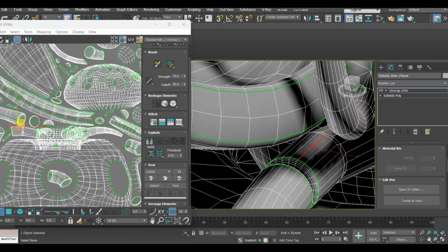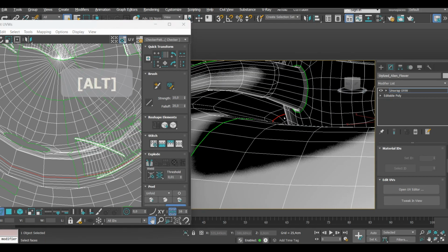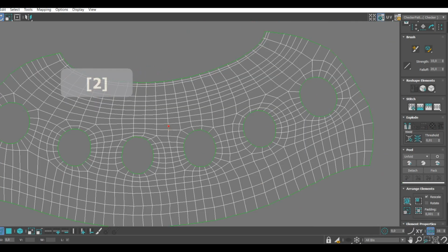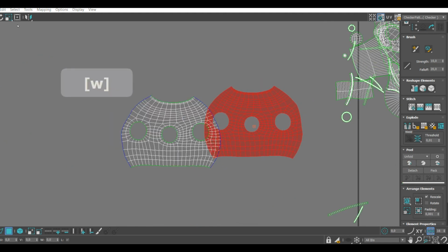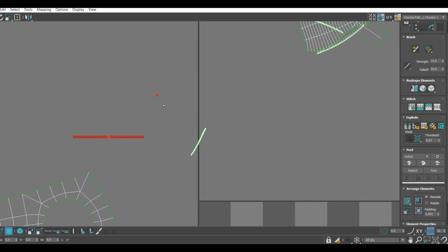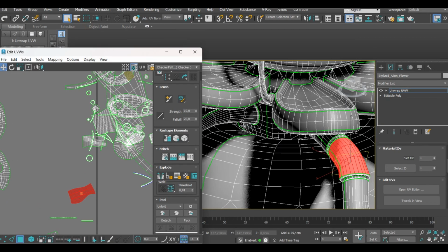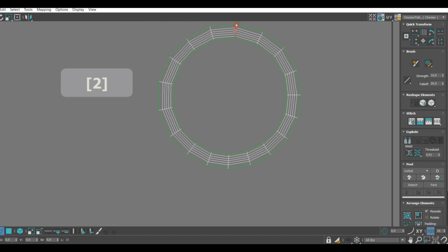My whole workflow here consists of 3 steps. Flatten UVs by smoothing groups that we have arranged on the previous stage of the process. Break all cylinders, and then flatten UV chunks and position them according to the desired texture flow. Also, I reshape some elements by straightening their geometry, break circles, and relax them just a little bit.